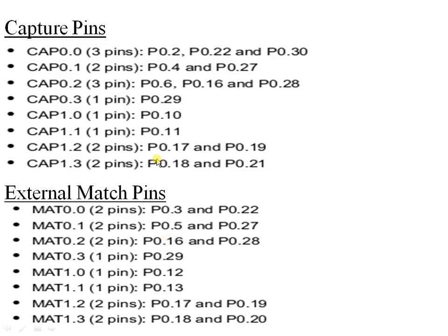These are the capture and match pins provided for this microcontroller. As you can see, CAP0.0 or CAP1.0. The first numeral, 0 or 1, indicates whether it relates to timer 0 or timer 1, and the second numeral indicates the channel number.